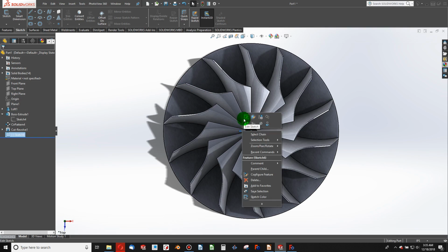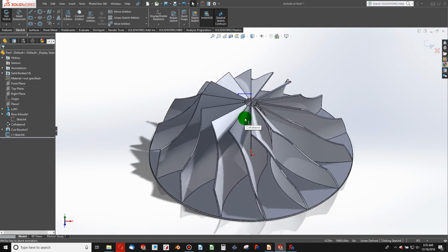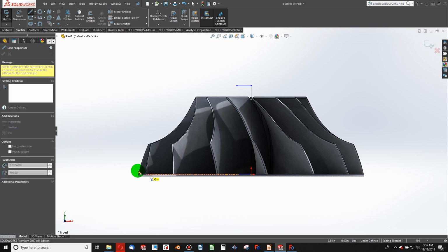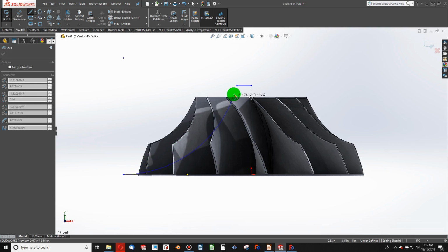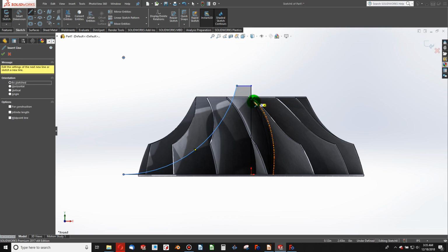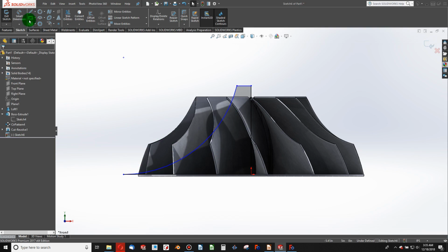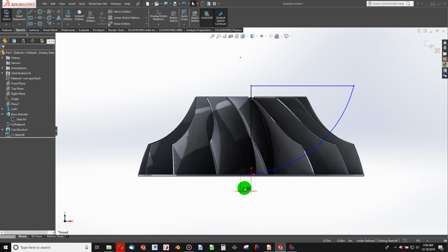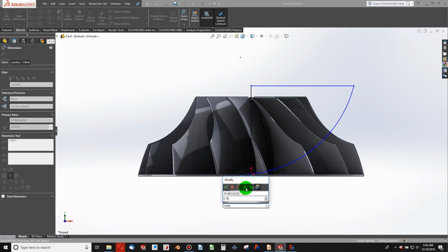Okay, now that that little perfectionism moment is over, there's a cool little feature in SolidWorks. If you're interested, I can start a line, and then I just bring this line back to this point, and it creates an arc, and so it kind of saves me a little bit of tooling there. Now I'll make this 3.75 rather.